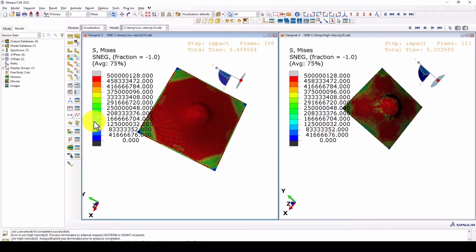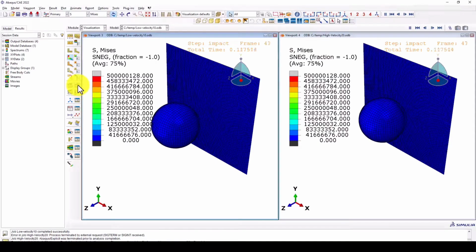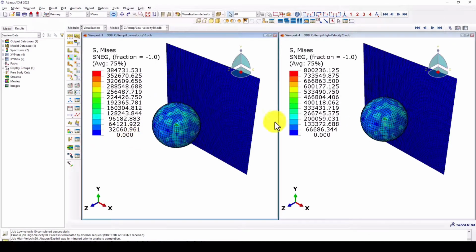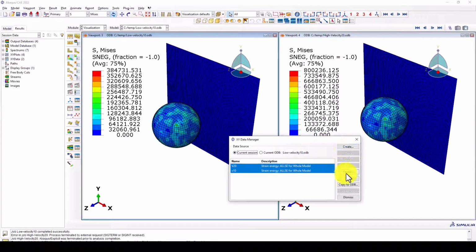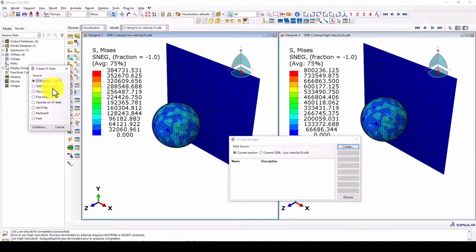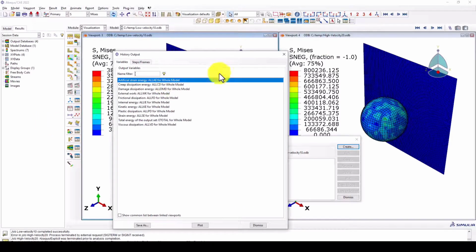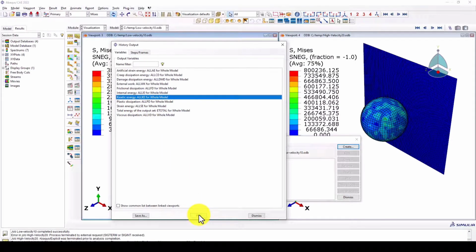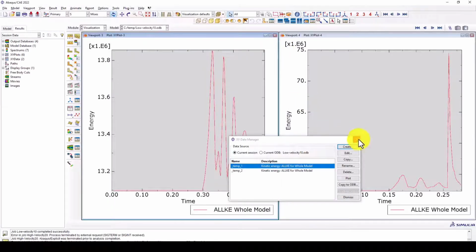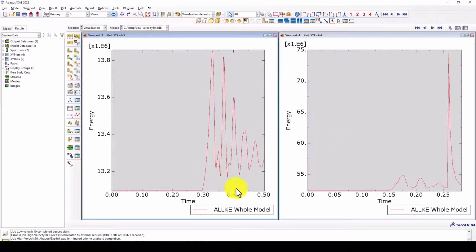In this explicit solver of Abaqus, we can define general contact for complex contact interaction. For a simple ball and plate problem, we can define the interaction between the ball surface and the plate surface. There are two fundamental concepts we need to understand, that is the normal behavior and the tangential behavior. For tangential behavior, we are going to discuss that later. For the normal behavior, we generally want the surface to resist penetration. A commonly used approach is hard contact in the normal direction. This means the surface can transmit compressive contact forces but should not physically pass through each other.